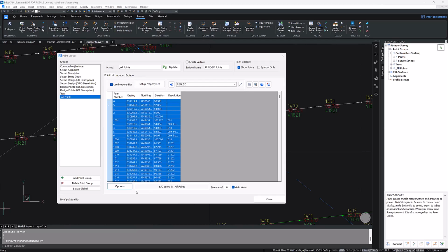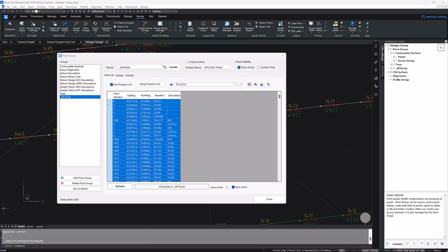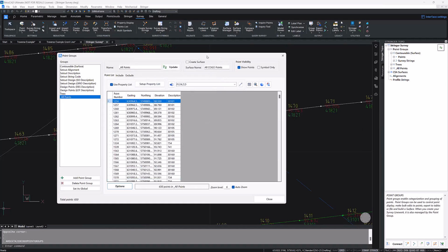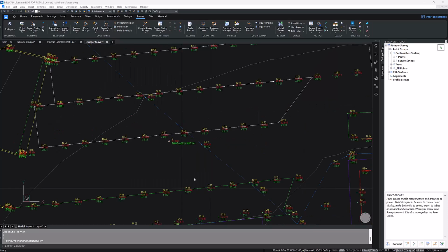I'm going to be setting this up to use these settings. So dropping down options, I'm going to go apply settings from code set. It's going to ask me, okay, which code set am I pulling these settings from? So this time I'm going to be using it from numeric individual layers, as that's the one that I have applied this to. The 201 code room is the one that we have modified the point style for. And that point style now holds that information.